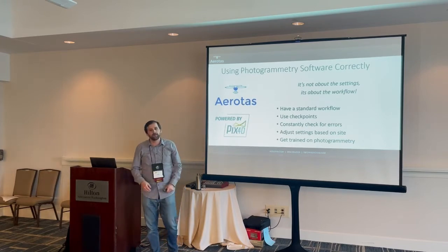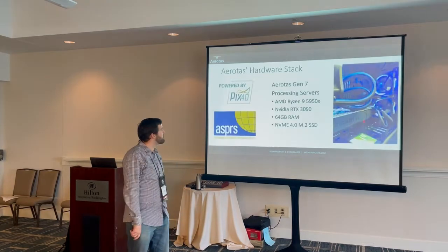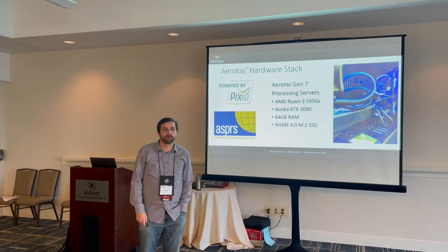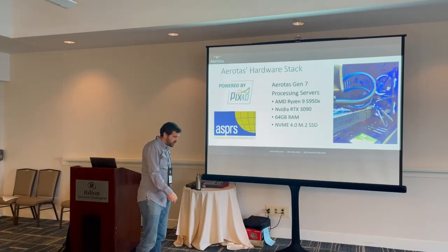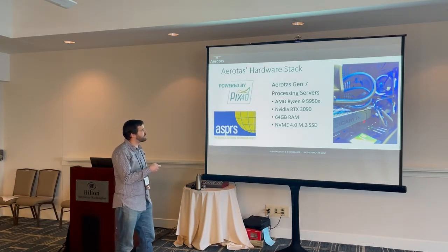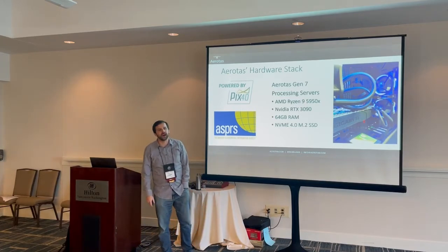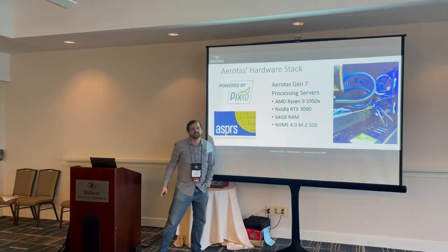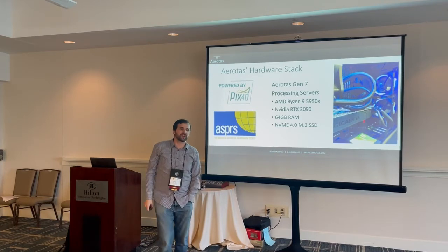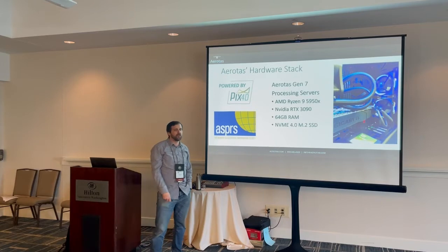Yeah, question? Just a random question on your system specs. Do you find that Pix4D works more efficiently on the cards that are built more for gaming as opposed to the ones that are built more for processing, like a Quadro or something? Great question, and the answer is Pix4D is generally not going to be GPU bound. It is going to be CPU bound, so the actual CPU processor is going to be the biggest difference. And that's where the Ryzen 5950s are going to be some of your most powerful CPUs. The GPUs help, but they're not going to be a major difference.